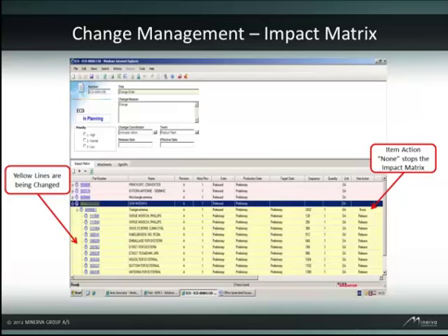So this assists the user in identifying what the consequences of the change might be. You are then able to define what you want to do as a part of this change with the item actions, and you're also able to control the target state, so the life cycle. Where are we right now in the life cycle and where are we moving to? This is the controlling parameter defining which type of process you are going through and which type of people should be involved as well.